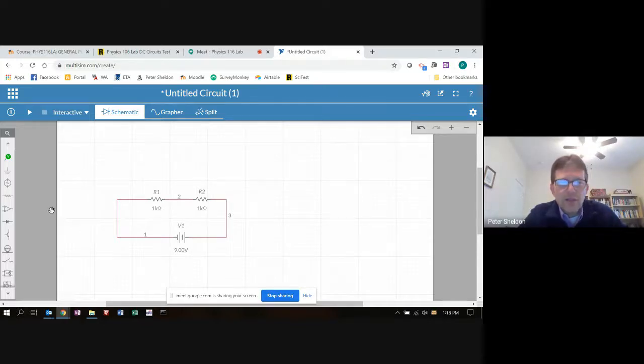Okay, so here's the thing that you have to do in Multisim. Actually, you probably don't have to do this, but I'm going to ask you to do it: we've got to decide where 0 volts is, because unlike in class, when you have a multimeter with 2 wires that you put across something, here we only have a multimeter with a single wire. This is the multimeter here, but it's just a single wire. It probably works just fine. I'm going to put it down right here. It doesn't tell me anything yet.